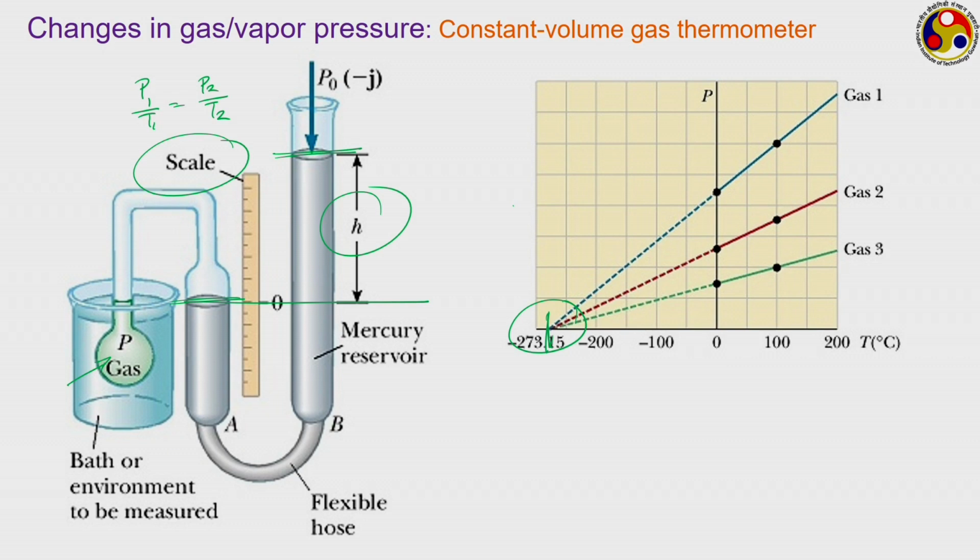Now, the constant volume gas thermometer generally is used as a reference for calibration purposes, but may not be for industrial use because it is generally fragile. Again, you need to keep this one in contact with the body where we want to get the measurement. It is quite difficult to use for practical purposes, and that is why it is restricted only to laboratory purposes.